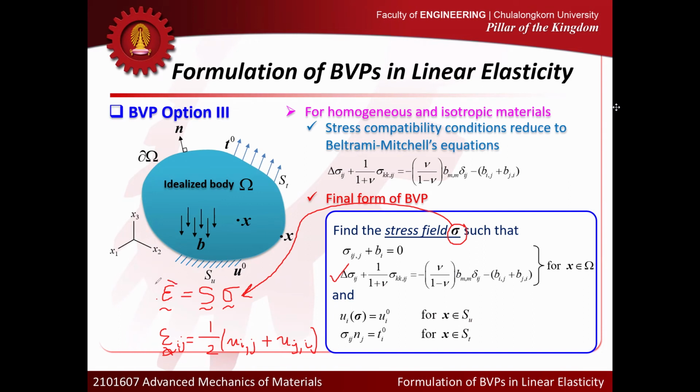It confirms that the strain generated from that stress is compatible. So once you have the compatible strain, when you plug it in here, this equation is integrable, in the sense that you can always solve this partial differential equation to get the displacement field. So the displacement field exists.